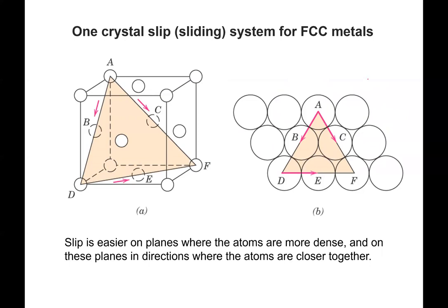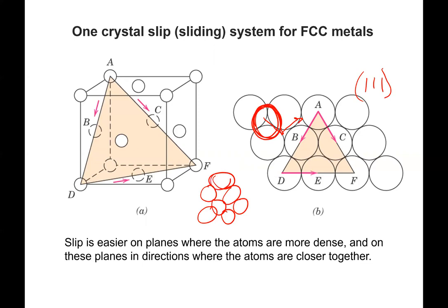So if you imagine the 1-1-1 plane for the face-centered cubic, and think of these as billiard balls now, imagine you've got this billiard ball sitting on top of these three, and if you've played pool at all, then you'll know that that ball doesn't sit very deep really at all. So you could push it relatively easily into this site and then back over here, which is where it wants to go. And it doesn't take a lot. If you were to have a plane like the 1-0-0, my drawing's not going to be great, I apologize.